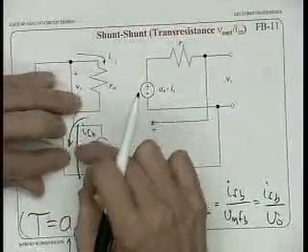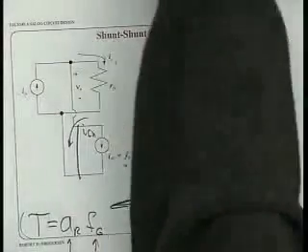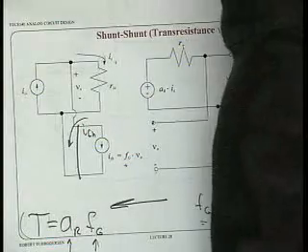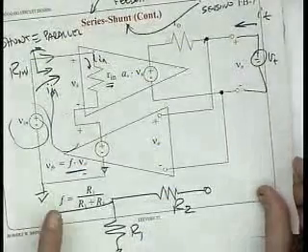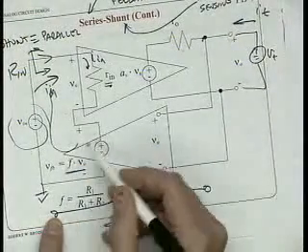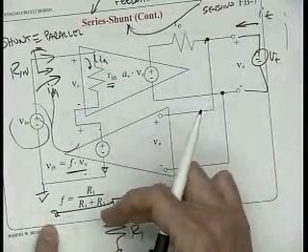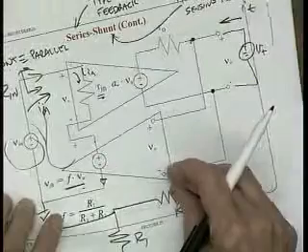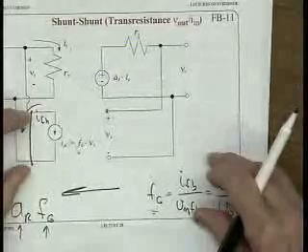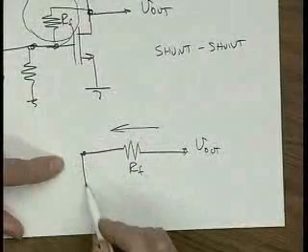We can take the feedback network and short it. If we look back at our previous case, let me jump back a second. Implicitly, though I didn't say it, when I calculated this feedback factor, what did I put at the output here? An open circuit. I didn't short this output of this feedback network. I put an open circuit there because it's a voltage output network. So for a voltage output network, to find the value of it, what you need to do of a two-port is open circuit it. For a current output of a network, you need to short circuit it. So in other words, for me to figure out what the feedback factor of this circuit is, I will short this.